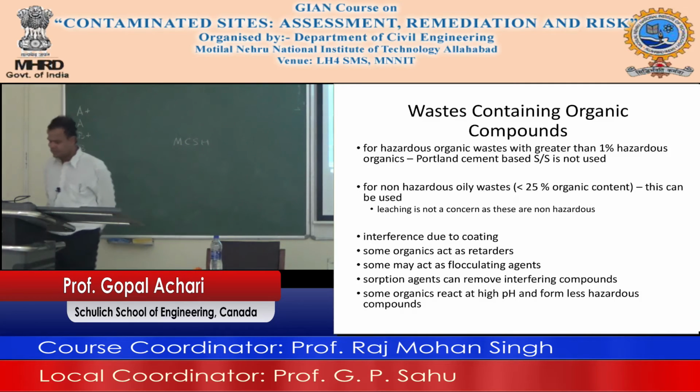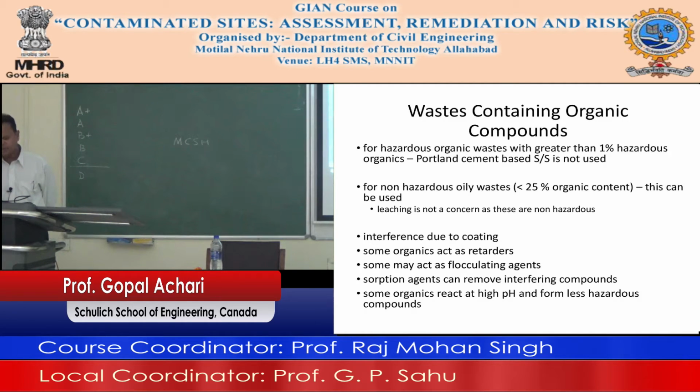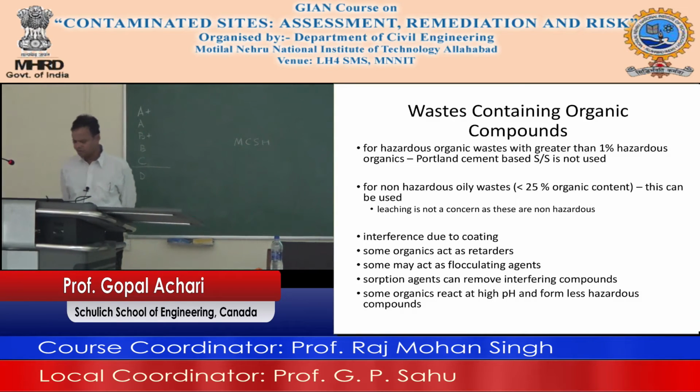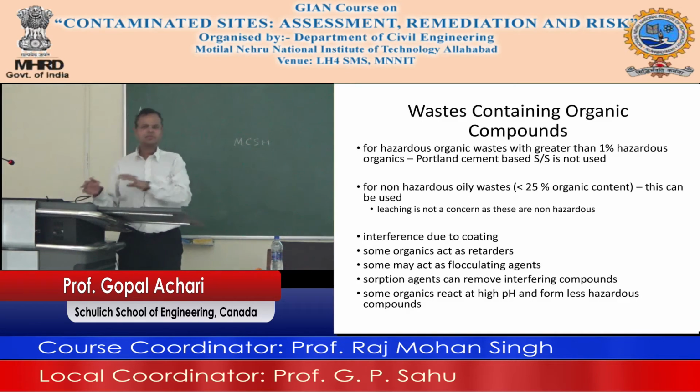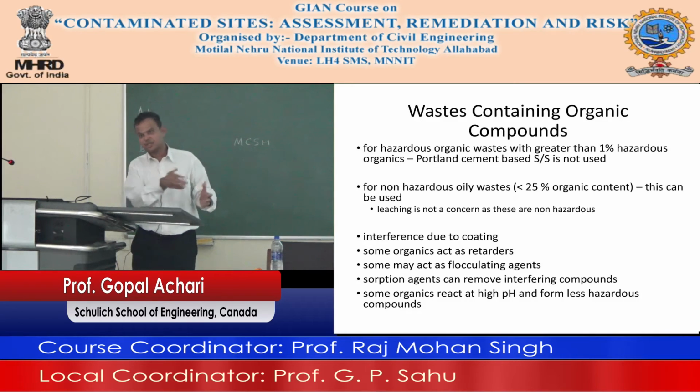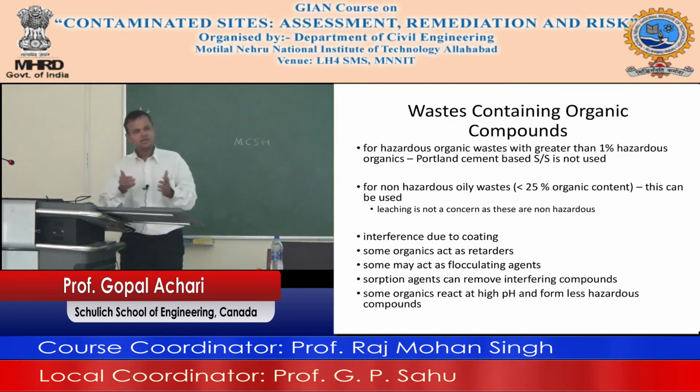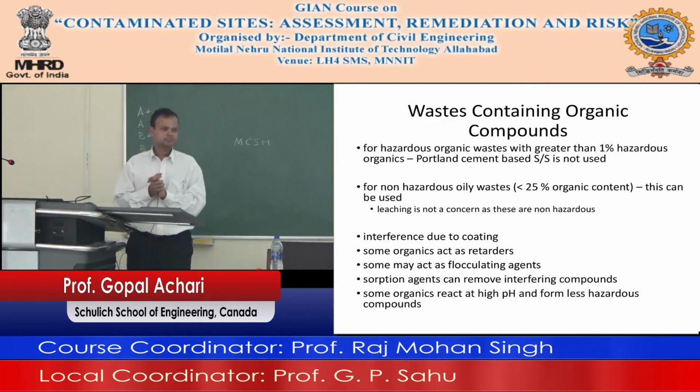So the reasons with cement are interference due to coatings. Some organics act as retarders. Organics may act as flocculating agents. Sorption agents can remove interfering compounds. Some organics react at high pH and form less hardener. So the bottom line is this: if you have organics, be careful using cement. If your organic is non-hazardous and leaching is not such a big issue, you can probably still use it to a certain extent, as long as it doesn't stop the setting and retard it forever. But if it is hazardous, think something else.